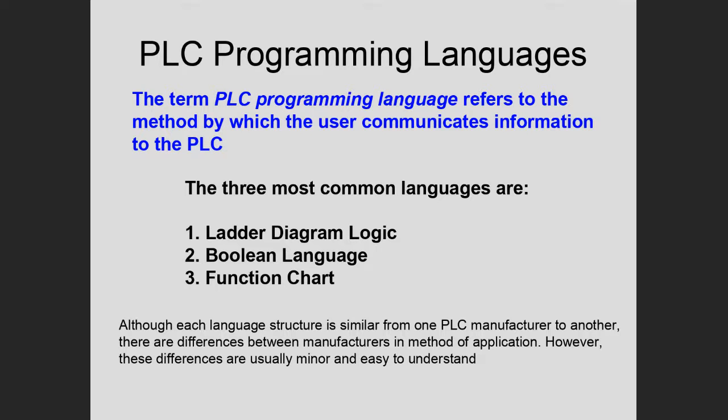Turns out there are other ways to program the PLC. I list 2 other ways here, and there are also other languages with which you can program the PLC. But we'll focus on 2 other types. One is called Boolean language, where you use the Boolean function you come up with from your logic to program the PLC. And what we want to focus on today is function chart programming. It's really not a programming language. It's more of a programming approach, and I'll explain the details in a second.